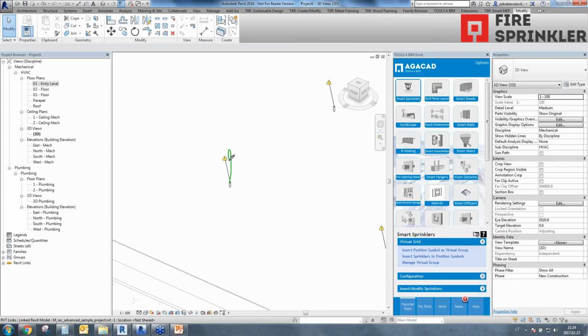So we have a pipe that is connecting sprinkler to some pipe that is placed here. So this is a sprinkler pipe. Here we have a range pipe, and somewhere here a big one we're calling the distribution one. So we have to have 3 different pipe types just to connect our sprinkler to the range to the distribution, and draw the distribution line.